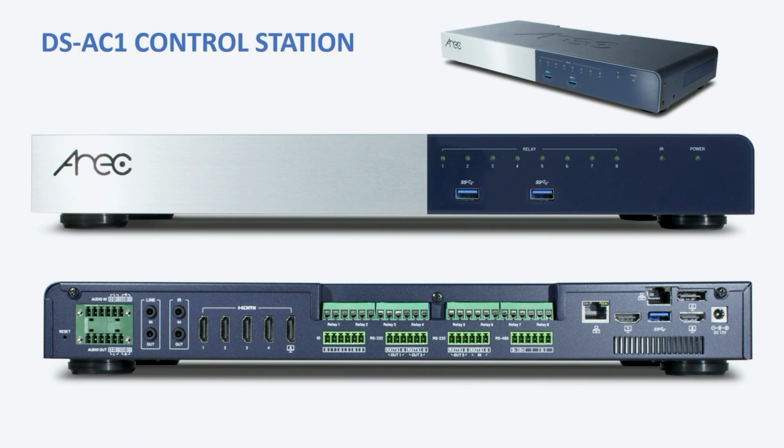On the back, there are control relays. So you could simply connect the cables for that. There is also GPIO, multiple. There is RS-232, 3 of them to control other devices. One also as an input to control the DS-AC1. Then there is also RS-485, which you can also use to control other devices. This DS-AC1 is able to control devices through network. You can do up to 8 TCP connections at a time. And this also supports infrared input and infrared output.